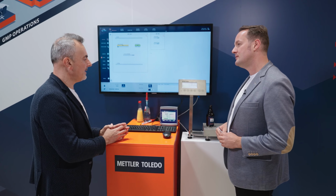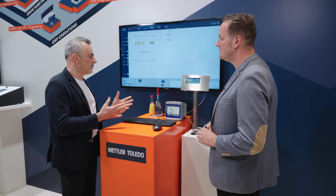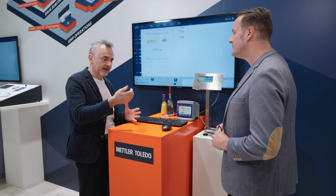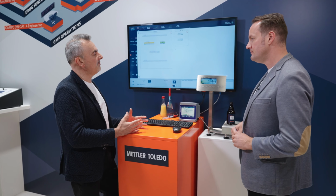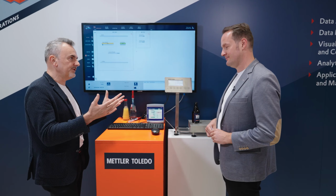How did you get this equipment ready for MTP? Good point. Mettler Toledo, of course, is a global provider of instruments for laboratories and also for production. At the moment, those instruments are not MTP ready, so you cannot directly connect and plug them in as an MTP device. In order to enable those devices to be MTP ready, we use our famous MTP gateway. It's a software application where you can connect the instrument on one side, and on the other side, it speaks the language of the MTP.